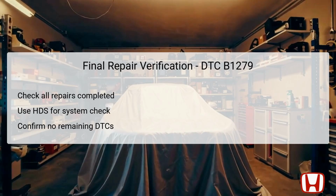Utilizing the Honda Diagnostic System, HDS, run a complete system check to ensure that no remaining diagnostic trouble codes, DTCs, are present. It's vital to confirm that the dimmer switch circuit functions properly, including the high and low beam operations. Ensure the indicators are functioning as expected, and conduct a visual inspection of all wiring and connections for any potential errors or irregularities. This step guarantees that the vehicle is safe and operationally sound post-repair.